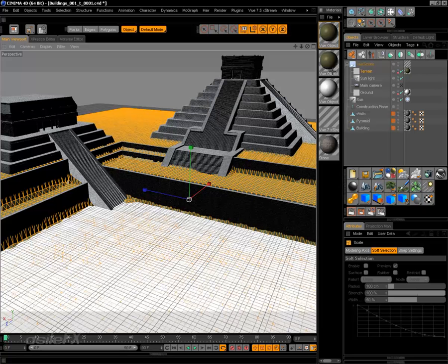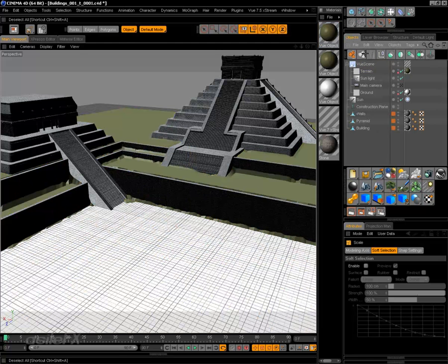And we do have one duplicate object being created, or a duplicate material proxy, which can sometimes happen. If we run into any problems because of that, hopefully we don't, but what we may need to do is kind of save the object, load in a different material. We'll have to see how that plays out, but you can see that we have two objects that are the same proxy because of the way that was edited.